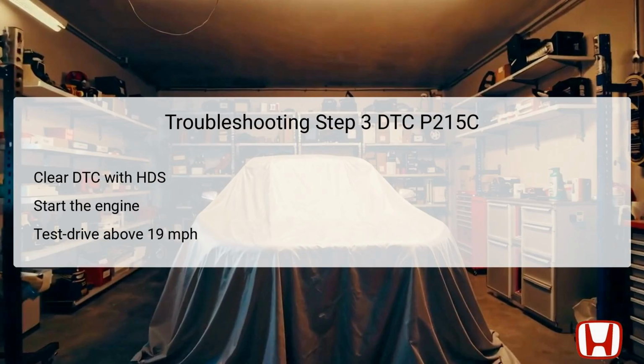The third step in troubleshooting DTC P215C is verification of the problem through a cycle of clearing and testing. Technicians should first clear the DTC using the Honda Diagnostic System, ensuring that any stored error data is removed. After clearing the DTC, the next action is to start the engine to prepare for a test drive.